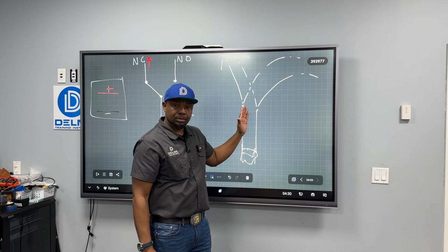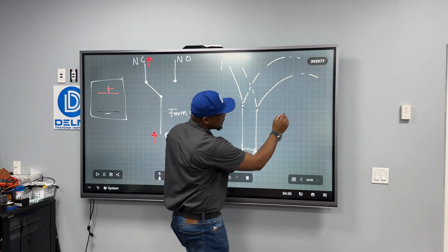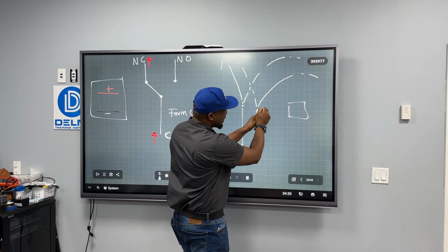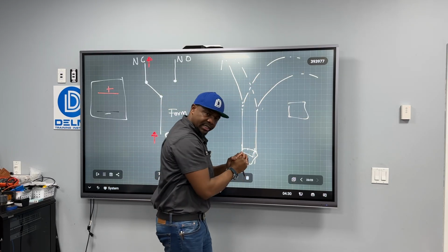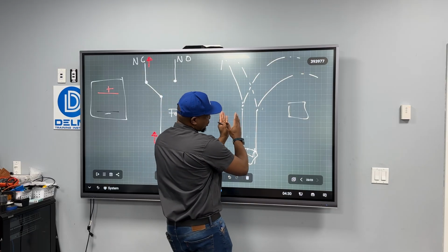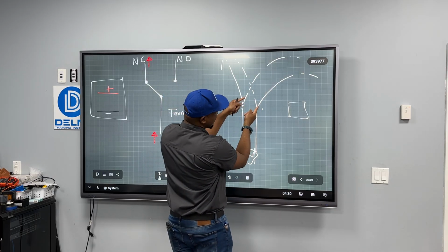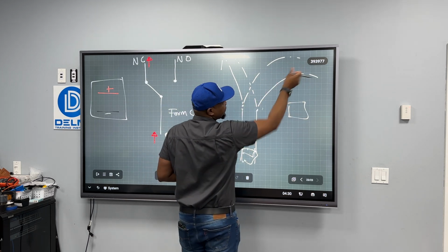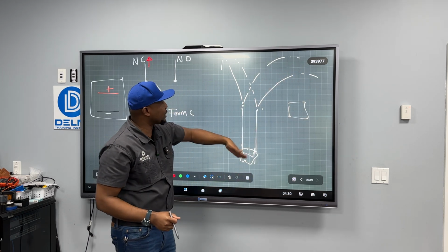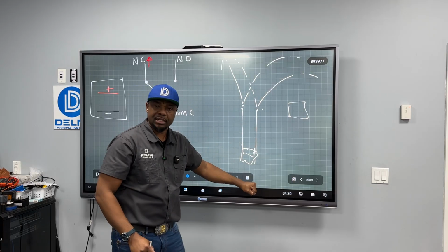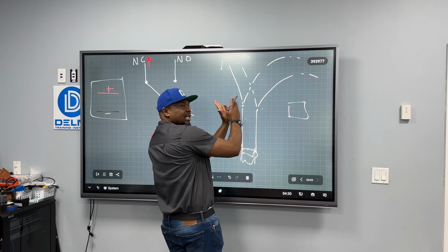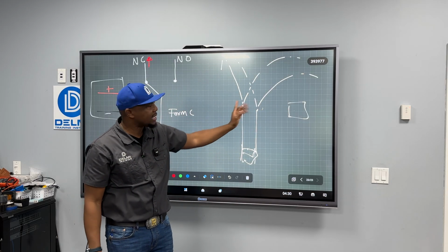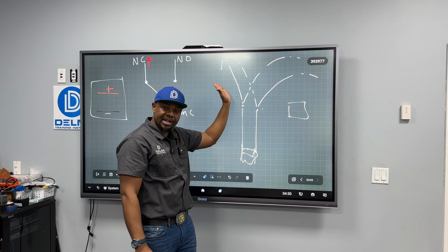it's up to the station guy who is here. Sometimes there's a booth here that a guy is sitting in. And he will get down and come here. There's a lever. He's going to hold that lever and pull it. If he pulls it down, this track switches a little bit to make contact with that. And then when the train drives, it's going to go here. If the next train gets here and it wants to go left, then he has to pull it the opposite way. And this is going to make contact with this so that the train can go here. So the guy who is here is the one directing the path of the trains.